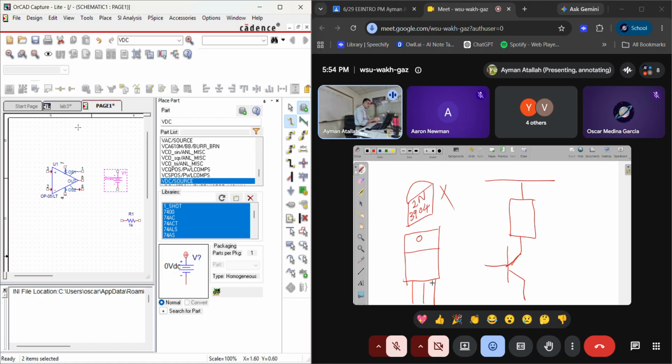What will happen is I'm going to get the current from the operational amplifier that will open and close the switch, the transistor. So this is like a switch here, but the motor will get the power from the power supply itself, and this is ground here. The output from the operational amplifier will close or open this.